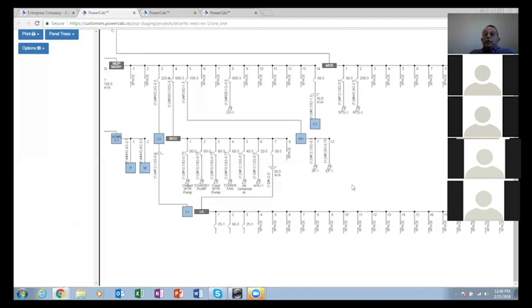So again, set up the panels and the distributions and the main, and then interconnect them as you go. And also leave everything on auto. All the program needs from you, as we discussed before, is the 3 inputs: the kVA, the load type, and the number of poles. And then let the system do its thing for you.